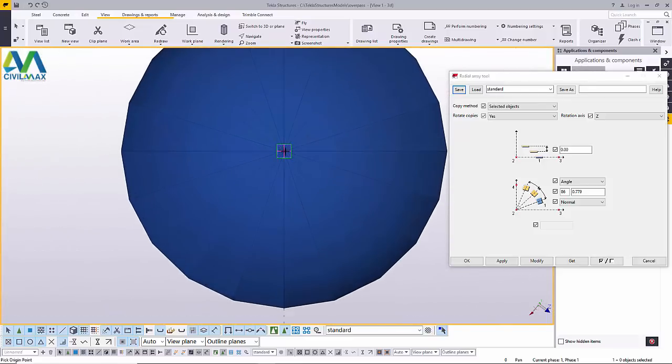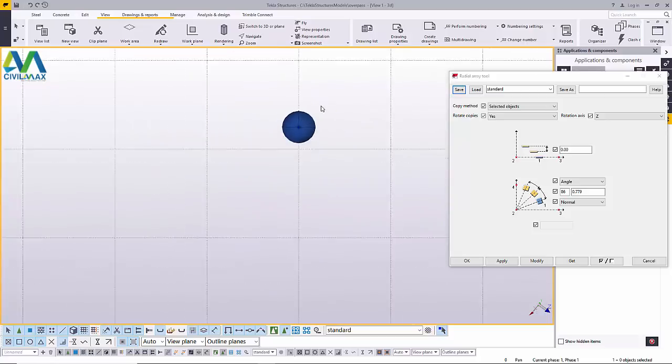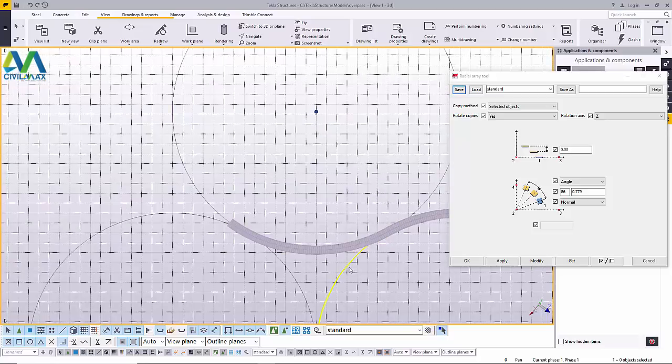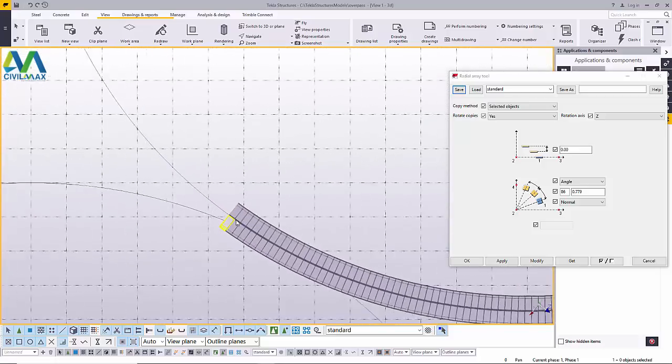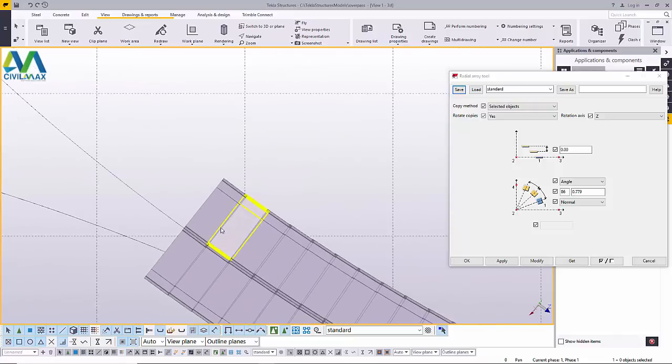We'll pick on the midpoint, then press our middle button on the mouse, then define our x axis will be that, and our y axis will be in this direction, and we'll press our middle button on the mouse. If you zoom out, you'll be able to see we have that following in that direction perfectly well. And we want to check this.